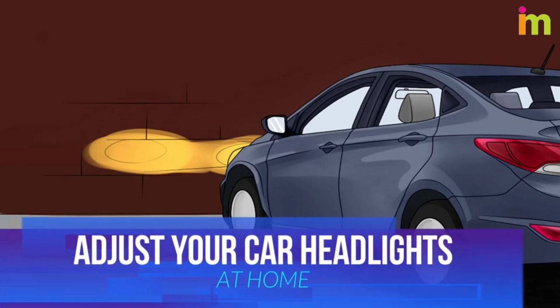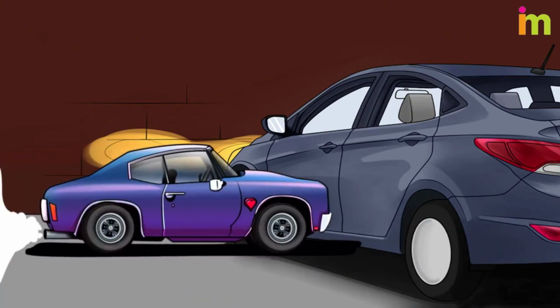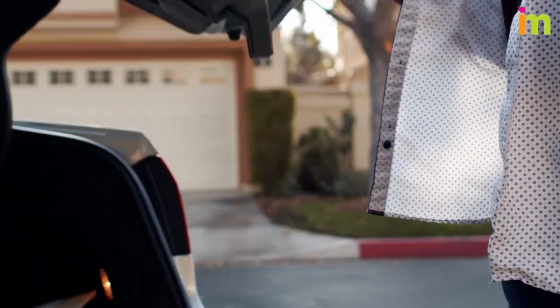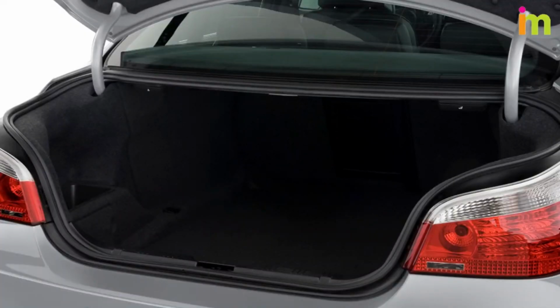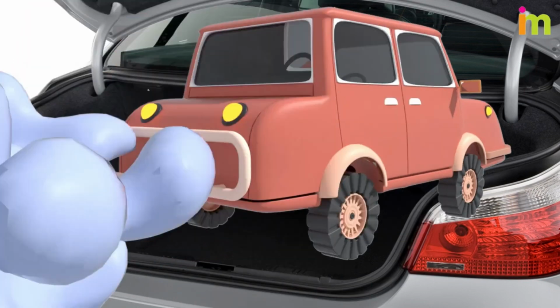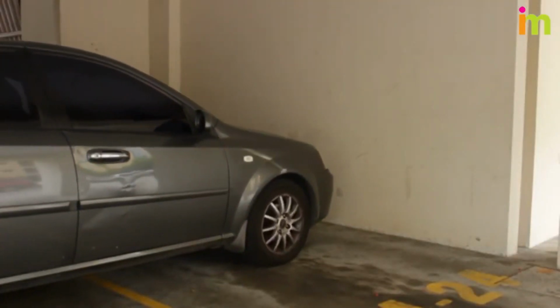In this video, I am going to teach you easy steps to adjust your headlights at home. First, remove any excess weight from the trunk of the car. Make adjustments to get your vehicle to its average weight and height. Park your car on level ground, facing a perfectly vertical wall.